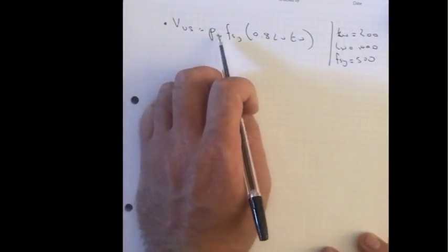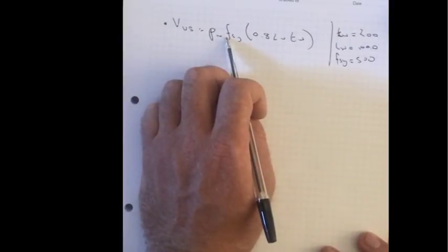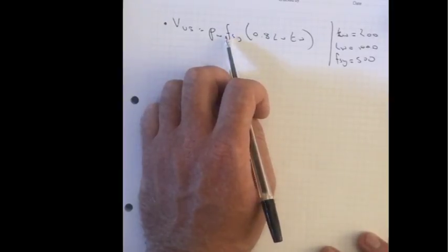And we have here the reinforcement ratio. If you look at 11.7.1, in the vertical direction it is at least 1.5%, in the horizontal direction at least 2.5%. In our case, it is the lesser of the two, so it'll be 1.5%.